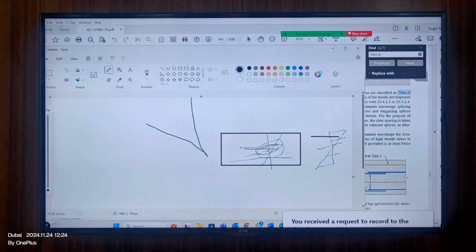At this portion actually, why should I provide the same spacing and the same diameters that we need to follow for the starter bar? The starter bar horizontal reinforcement is only provided for two reasons. One is for confinement, another one is for lateral stability of this rebar. If I don't provide anything, the rebar will not be stable, right? So I need to provide it.